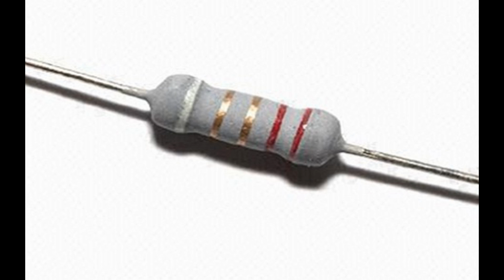Definition: resistance tolerance represents the range within which the actual resistance of a resistor is expected to fall relative to its nominal, marked or rated, resistance value. It is usually expressed as a percentage of the nominal resistance. Tolerance values: common tolerance values for resistors include 1%, 2%, 5%, 10%, and 20%. The lower the tolerance value, the more tightly the resistor's actual resistance is expected to match its rated value.